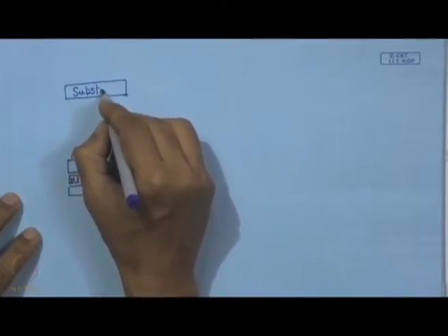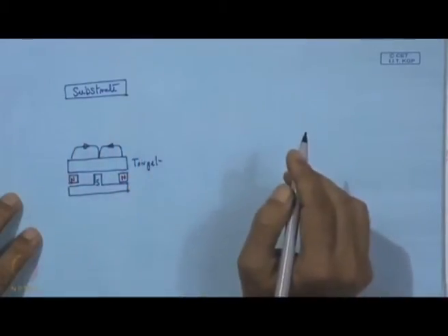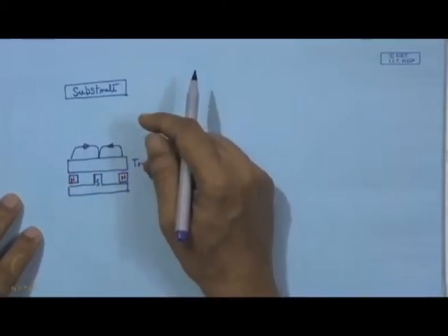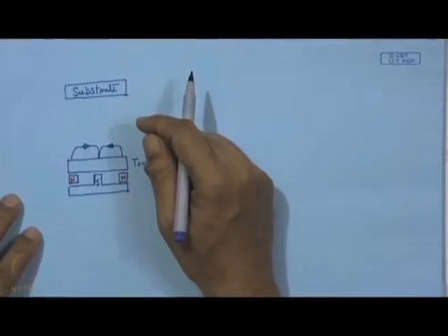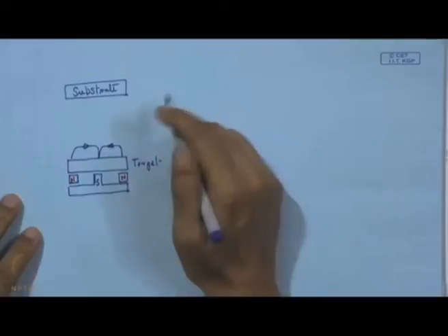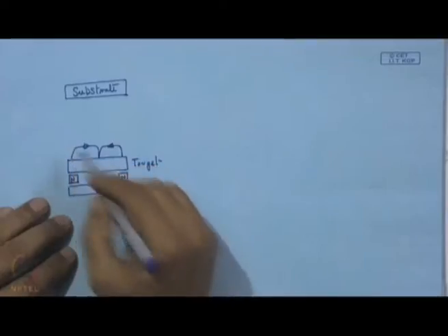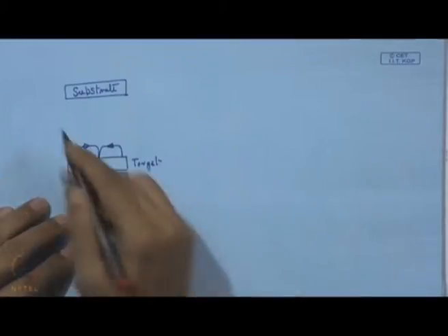This will be the receiver, the receptor surface, where the flux of sputtered coating material will be intercepted and come in the form of a condensed film. Here the existence of the plasma volume is very important.